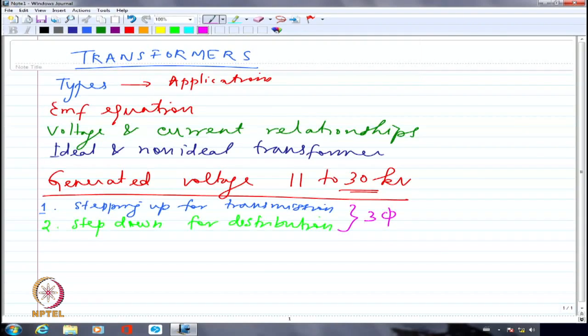This particular railway electrification is done with the help of single phase AC because the return route is not there at all. Return conductor is not there at all. The rail serves as the return conductor. There will be generally a line which is the overhead transmission line, somewhat like this.